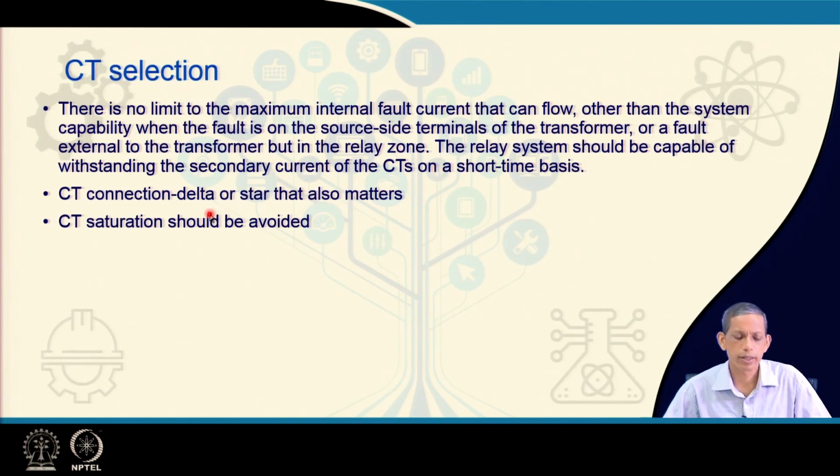CT connection can be delta or star. We will see in later literature the star or delta connections to address the phase shift issue, and we will discuss that in a later class. But in the numerical today, the CT connections considered can be star connection on both sides, which is what is preferred these days.